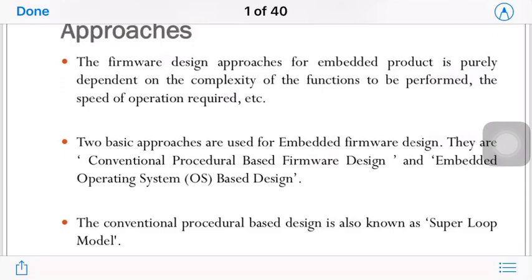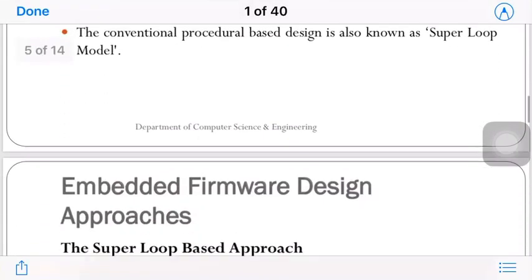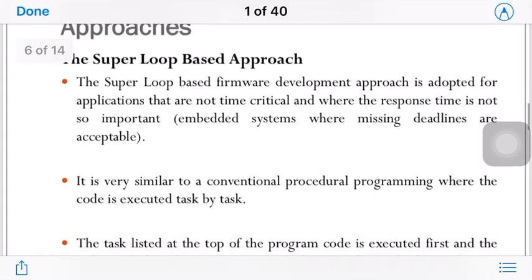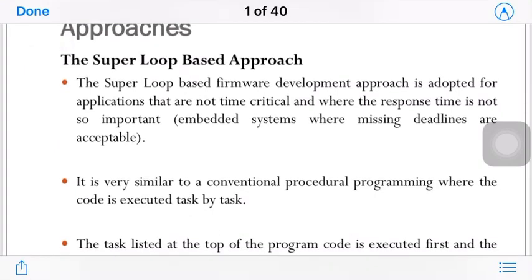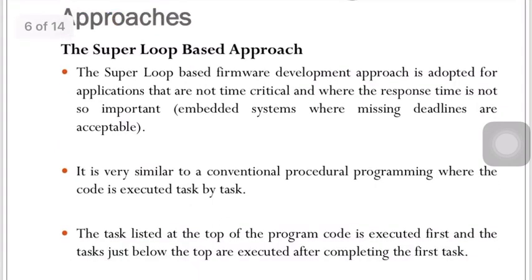The first approach is also called a super loop model. The conventional one is also called a super loop model. So let's discuss that particular approach, the super loop based approach. The super loop based firmware development approach is adopted for applications that are not time critical and where the response time is not so important. So this kind of approach will be used where the applications are not time critical.